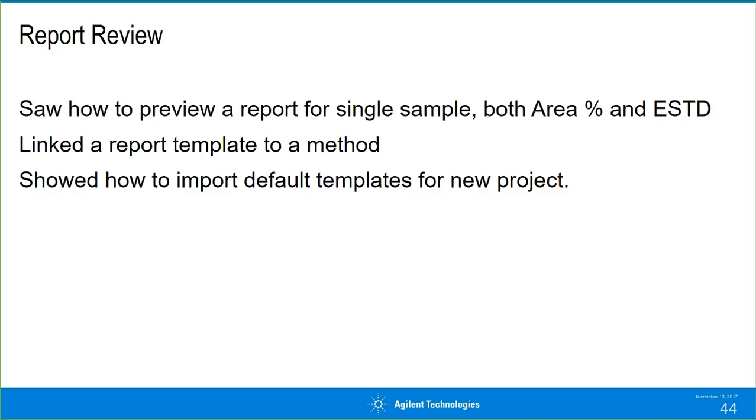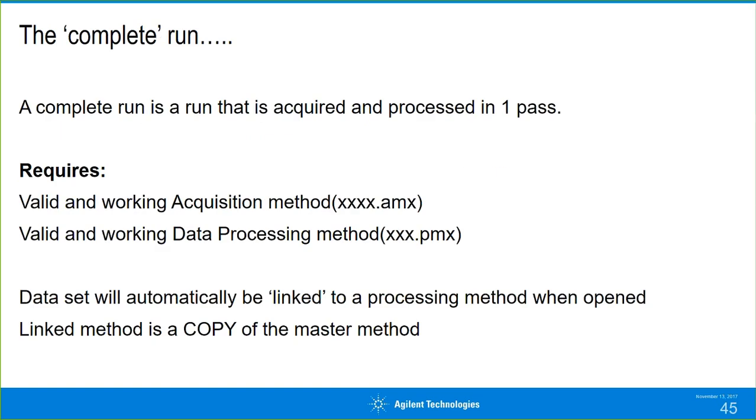Okay. So with that, we took a look at the report preview. We saw the sample injection, area percent, and external standard, how to link up two of them. And a really big thing here is to show how to import the default templates to the project. All right. So with all of this, we've taken the very beginning of acquisition, and we've run through the whole process. But to wrap all of this up and pull it all together,